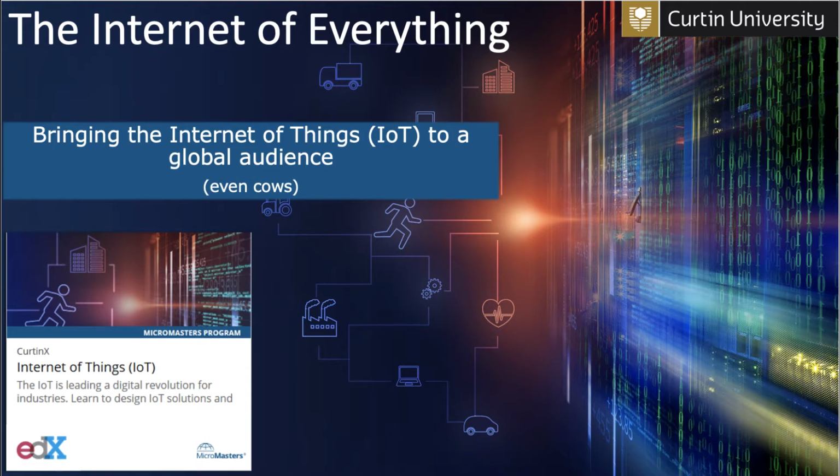So ESP32s are fairly popular these days, and the main reason is that they have a wireless and a Bluetooth module embedded on the microcontroller, so you don't have to deal with connecting a separate module to your micro. That's why they're popular. And as Ahmed says here, LoRa is low bandwidth, so you really shouldn't be using it to send images. So yeah.